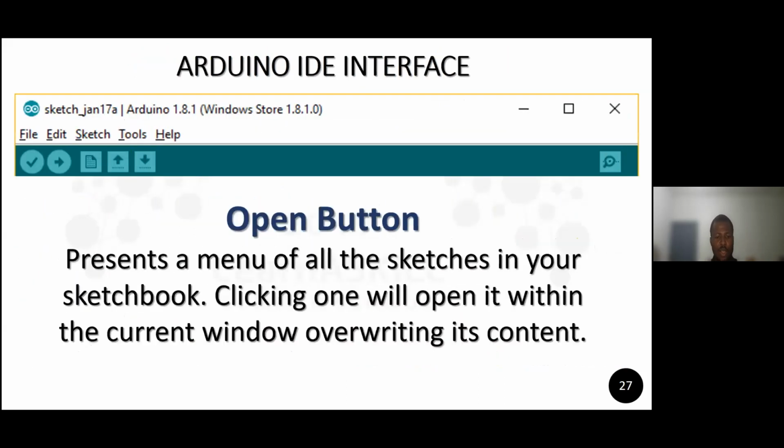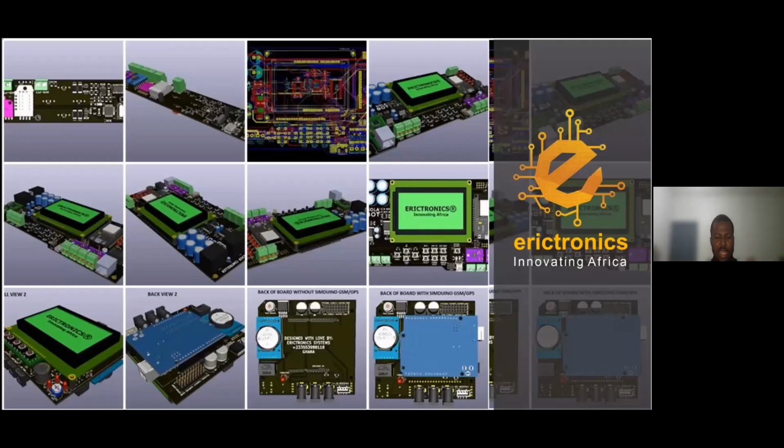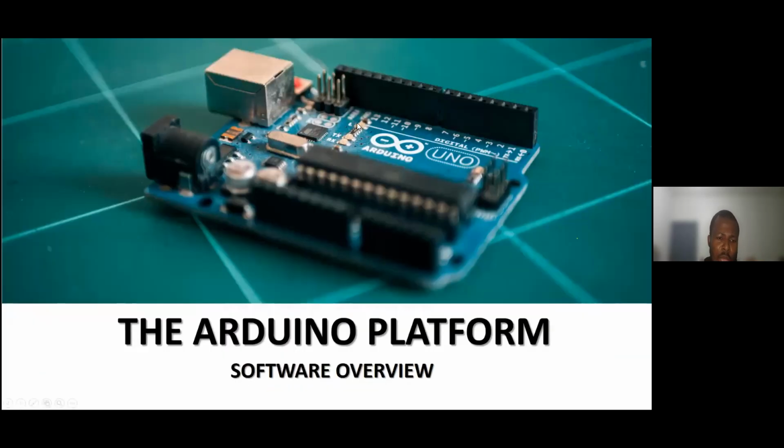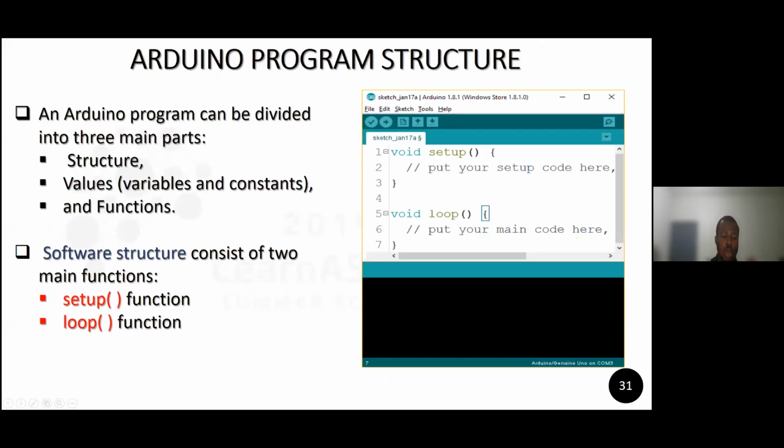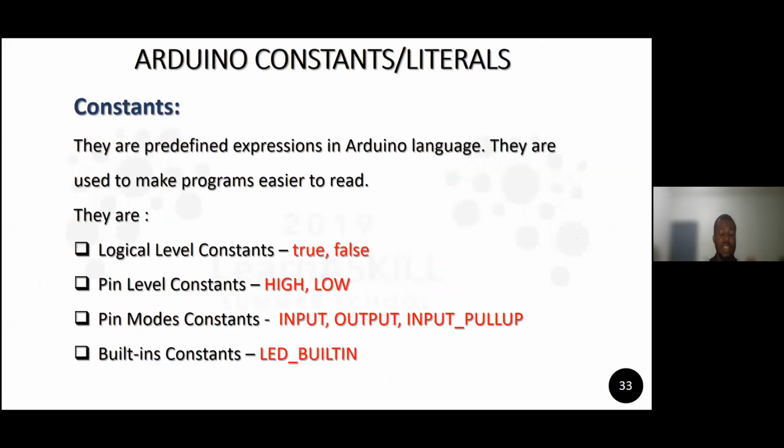There is an LED on your Arduino board that is connected to pin 13, which makes it possible to do hello world programs with Arduino without connecting external components. So you can just run a blink command and let that LED blink. To reference it, you can either use the number 13 or just say LED_BUILTIN. And please, these are keywords, so you have to type them as they are. If they are caps, you have to put them in caps.